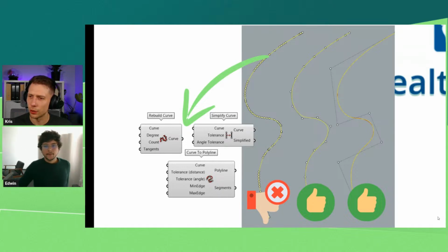Yeah, so the first thing you can do after importing some curves or geometry into Rhino, or if you have some geometry already in Grasshopper, is I really recommend to bake it and just click it, as you can see right now. Here you can see that lots of points are defined, and this is actually the definition of a really bad curve.